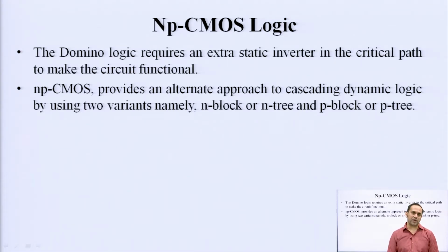So, some amount of energy is always lost in turning it on. To pass a logic 1 through an NMOS transistor will require a finite amount of positive voltage, the so called threshold voltage. P channel devices, on the other hand, work on negative threshold voltages. So, they can be considered as easy to pass a logic 0.